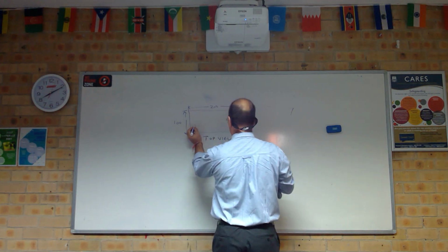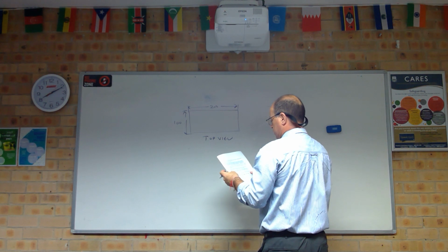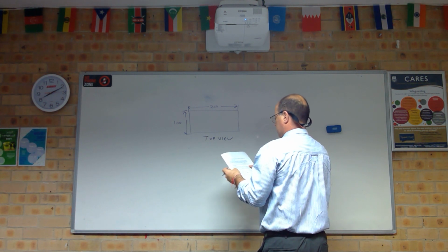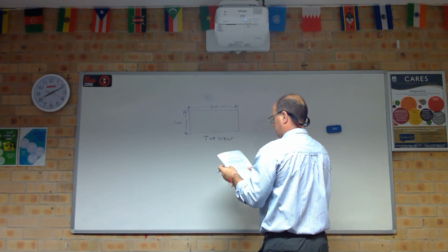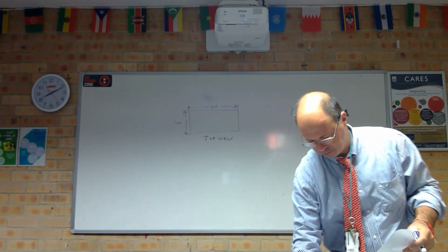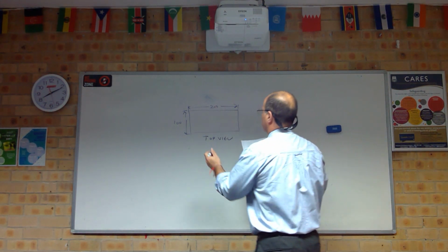And then it says draw two holes in any location of your choice in this top. So I'm going to do a hole. Make one hole a 12 millimeter through hole, and the other a blind tapped 8 millimeter by 1 hole with a thread depth of 10 millimeters. Use the PDF below to learn how to draw the symbol for a tapped hole. Now we did the tapped hole symbol. So one of them is 12 millimeters.